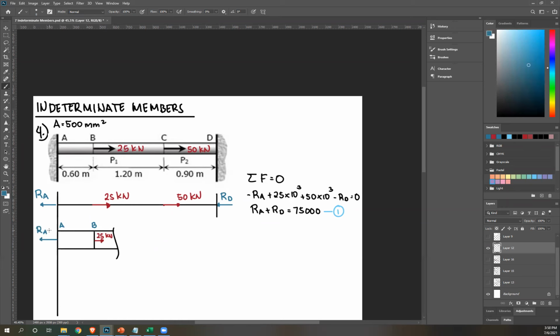Then you're gonna assume the direction of your force. Is it compression or tension? So this is just a guess. Maybe it's compression. I'm just guessing. Stress BC is in compression. Oh no, tension. Makes more sense. Okay. Why? Because this portion is pulling, but this is greater. So the amount BC stretches is greater than it compresses. So I'm just gonna guess the internal force here is in tension.